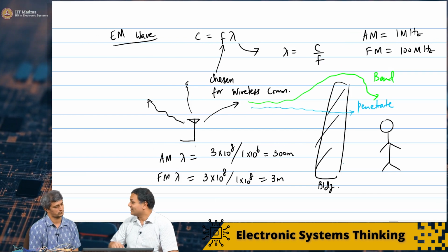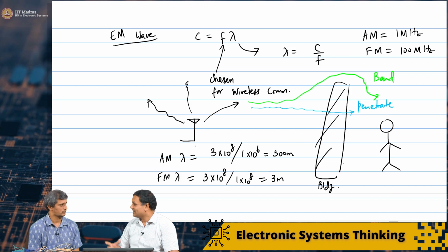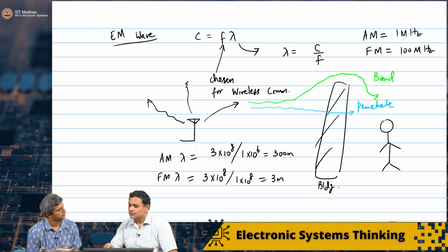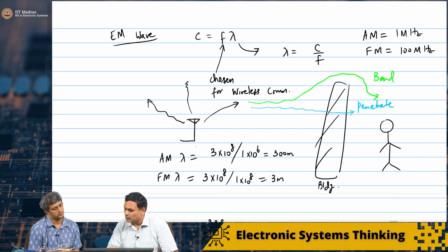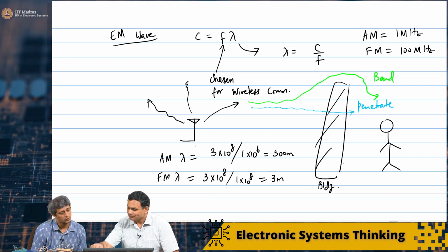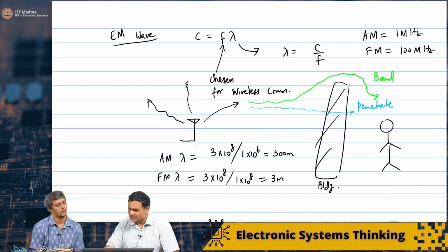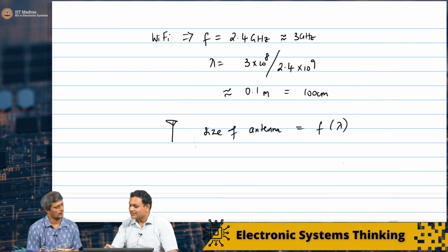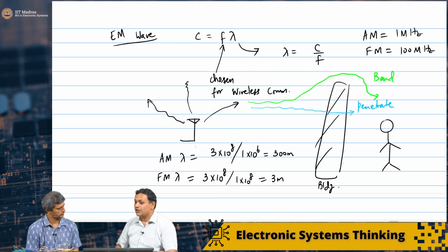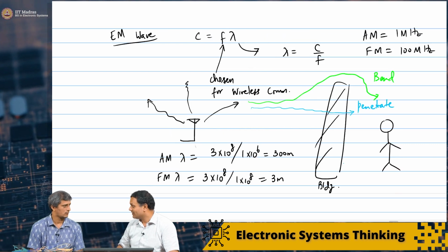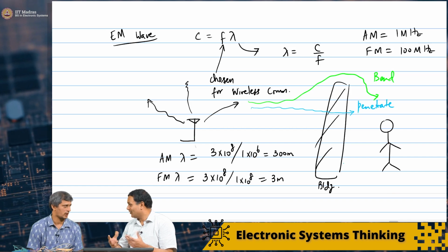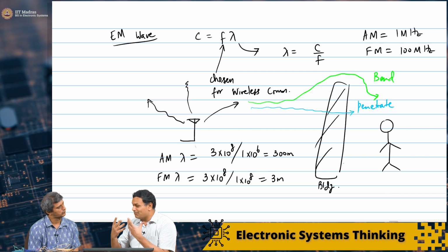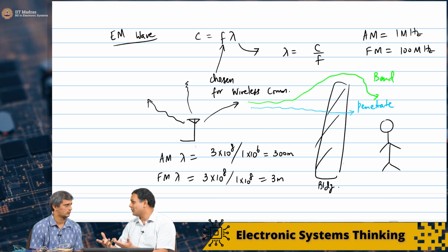Our discovery kit has a limitation of about 25 megahertz, which corresponds to a wavelength of about 12 meters. The antenna size is a function of lambda, so to send 25 megahertz you need a 12-meter long antenna or something similar. That is why we are building a very basic system, but it's good enough to demonstrate the concept.